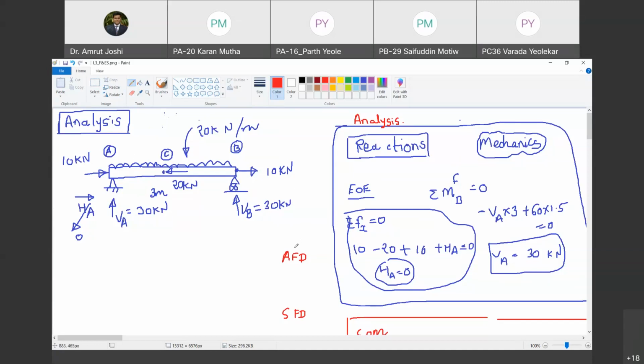Yes, sir. Now, just on the top of this axial force diagram name, I am going to draw the sign convention. So what is our sign convention? If this is a cross section, or if this is a section that we are considering, a pair of equal and opposite forces which try to compress the cross sections adjacent to this section, we are going to treat it as compressive, and we are going to treat it as negative.